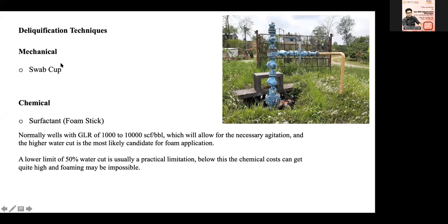because if you are exceeding the tensile strength of the wireline, you are going to lose your wireline, and the swab cup as well as the wire will drop into the sump. You are going to require some fishing job, which will cost more.